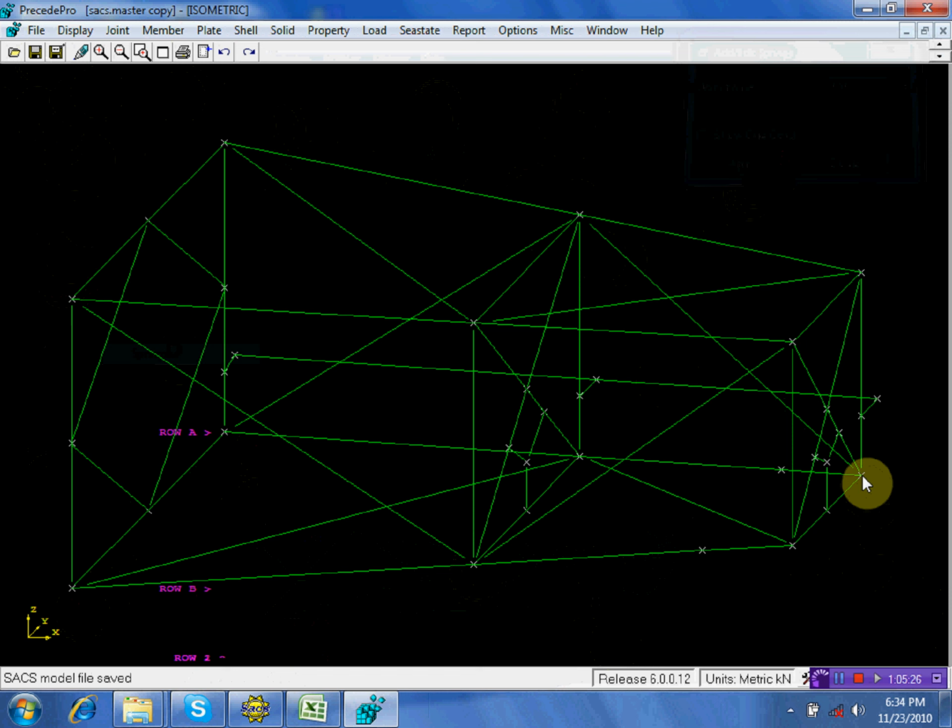Now, it is unlikely for a skid beam to be in this direction. It should be horizontal. But for analysis purposes, we will utilize this one. Okay? You understand? So, a skid beam should be like this. Have you seen a skid beam like that? No. It should be like this, horizontal, right? But in our case, it's tapered. So, I will add a gap joint.